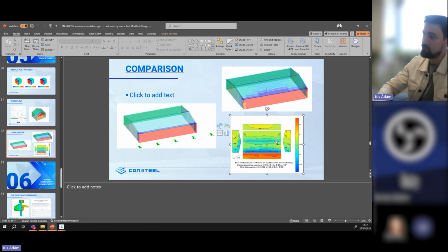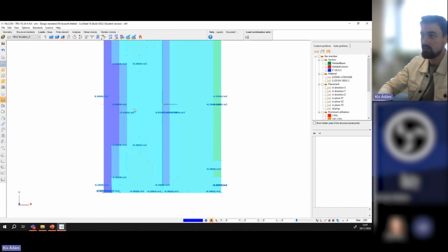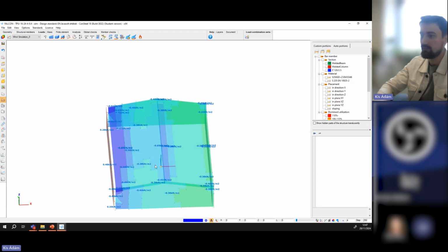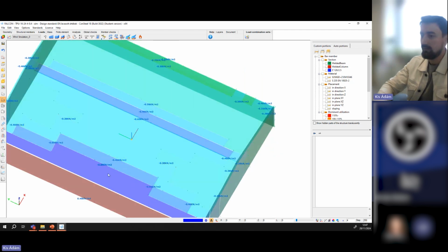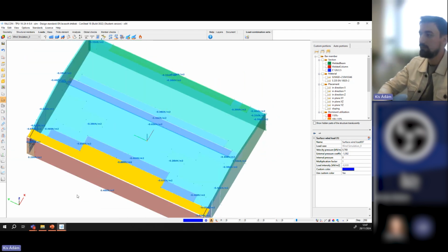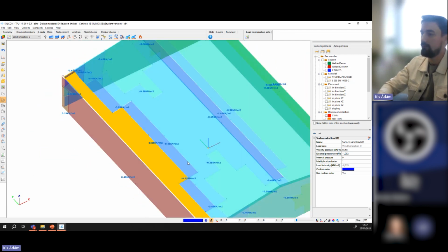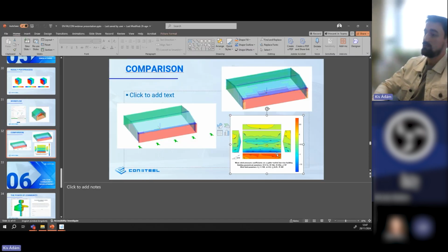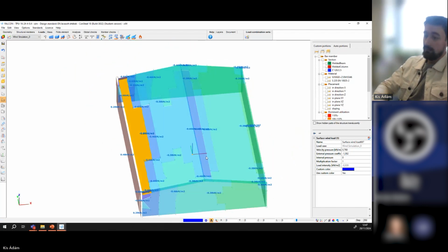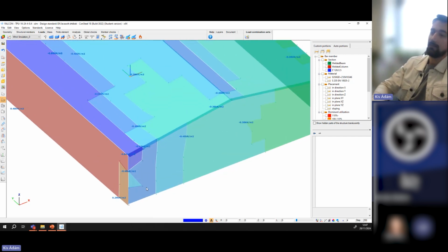which we can see also in the simulation, that we have these higher values in this region, and that minus 1.1 value for the external pressure is quite close to that range that is according to the wind tunnel test. So this is a simple scenario where we can also capture things like disturbances according to the mesh.